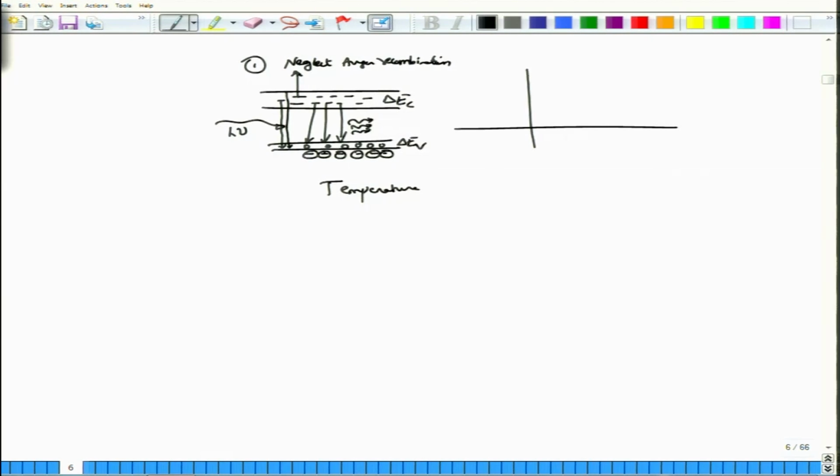So if your optical signal is between that, then instead of absorption and loss of signal, what you actually see is a gain, right. If you look at the transmission, initially there won't be any gain until the energy reaches a minimum of Eg, and thereafter you will actually see a gain, okay, and then it drops out and becomes absorption, right. So I am representing again log of transmission, but not the magnitude, okay. I want to show the gain and the loss here. So this is the gain term, and this is where the absorption is happening.